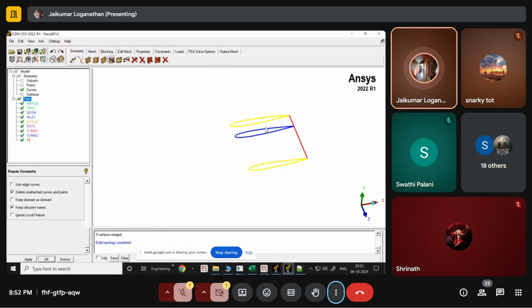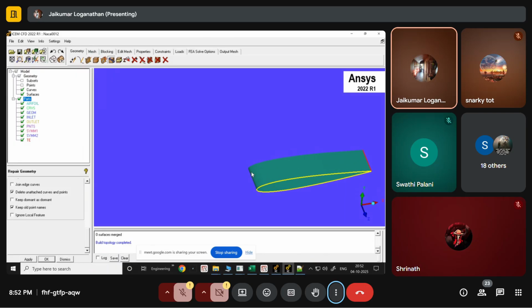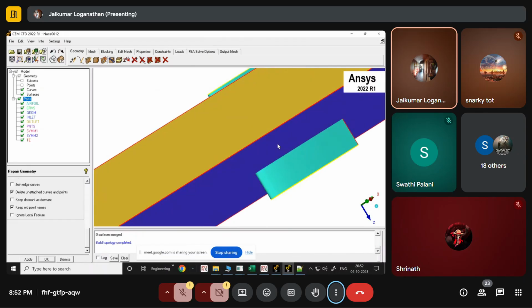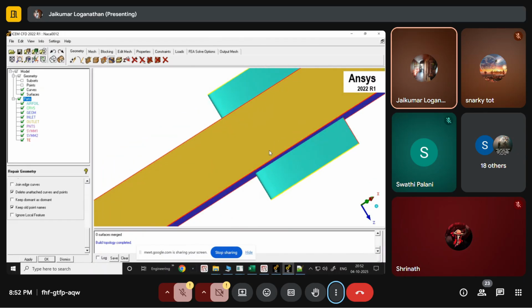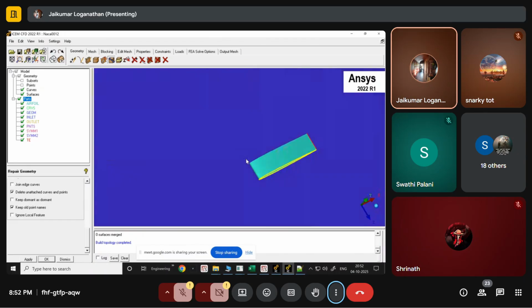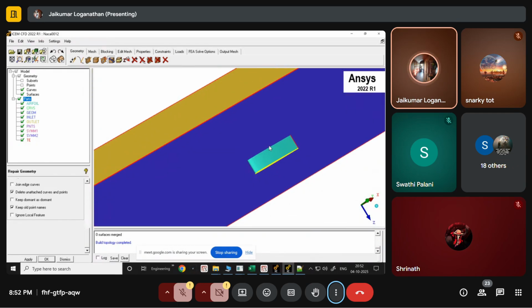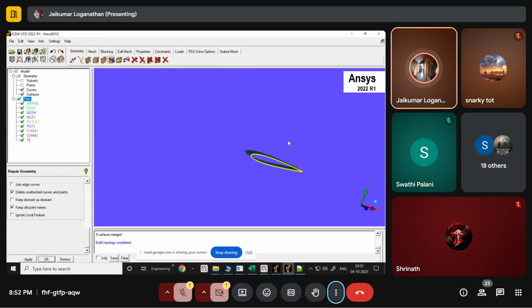It's okay to go forward. So let's go to surface and see. So this is where it is intersecting. Right. Okay, so let's do one thing. Let's create those intersection curves just to be sure. Otherwise, while creating mesh, it might create some problem. Okay, so what we're going to do is intersect this surface and the airfoil surface so that those boundaries are properly created.